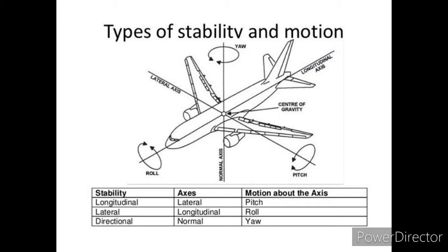Now, looking at the figure, you can see the horizontal rotation about the Z axis, which is called yaw. Again, you can see the motion around the y axis, which is referred to as pitch. Typically, pitch is associated with angle of attack. The plane can also rotate about the x axis, leading to the motion called roll.